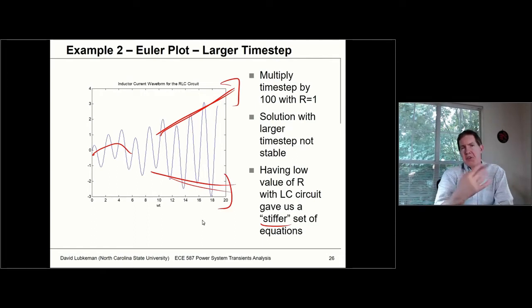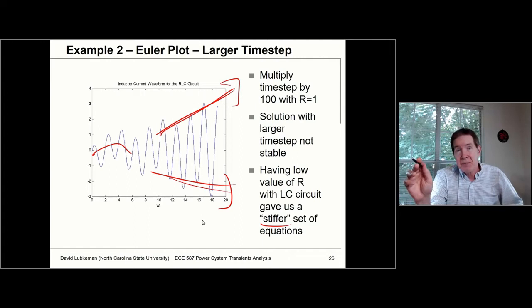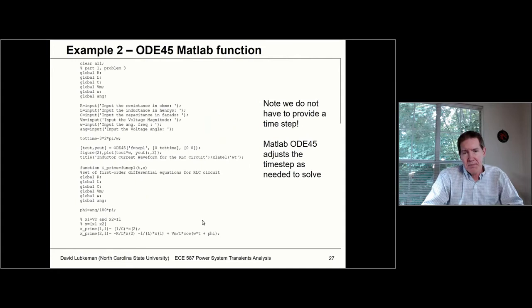And so if you were running, say, any simulation like PSCAD and that time step is too large, what'll basically happen is you'll have a voltage or current just going to infinity, and you won't get anything that looks like the solution you're supposed to see. All right. So anyway, this is what we have to watch out for in the Euler approach. We can get it to work if we keep the time step extremely small, but it's very prone to error when you have these underdamped situations.